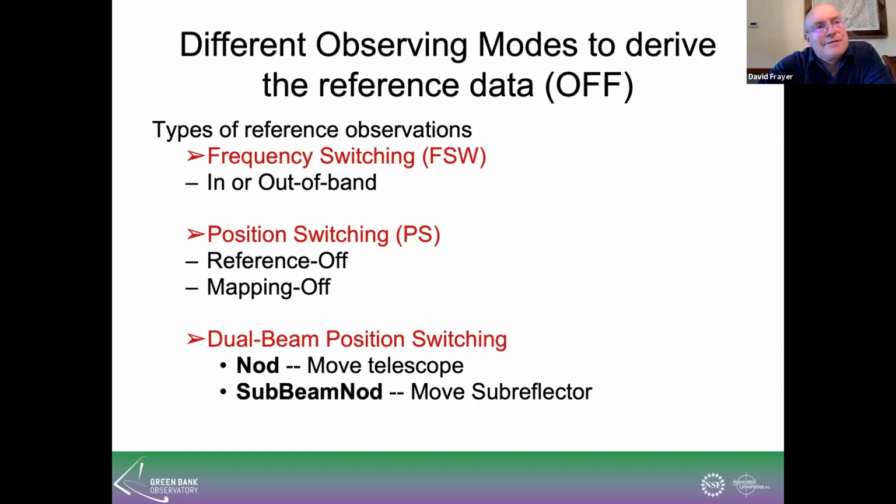I guess I didn't want to show, we have all kinds of extra slides to show this graphically. Maybe we should for these training workshops. But anyway, your noise within your passband stays the same. You switch the frequency, and you can actually see the signal, and all the instrumental passband effects get canceled out. And that's called frequency switching, changing frequency.